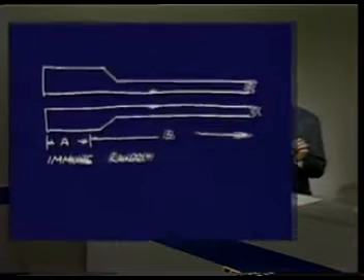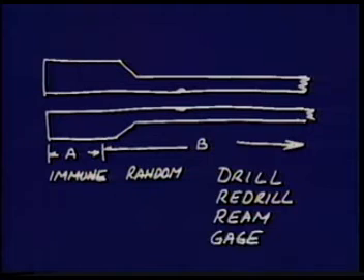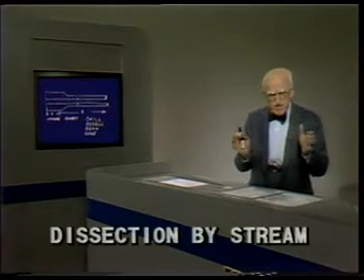We saw an example in the case of the gouged gun barrels. There, the gouges showed up at the end of a sequence of 3 operations: drill, re-drill, and ream. To dissect the process required 2 added gauging heads for the air gauge. Then we discovered that the first operation was guilty. A second form of dissection is by streams.